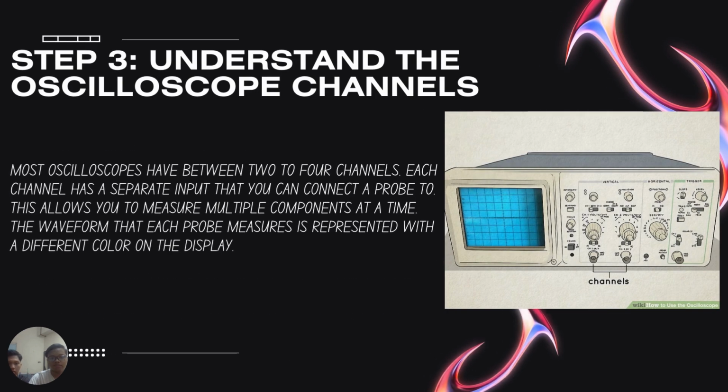Step 3. Understand the oscilloscope channels. Most oscilloscopes have between 2 to 4 channels. Each channel has a separate input that you can connect a probe to. This allows you to measure multiple components at a time. The waveform that each probe measures is represented with a different color on the display.